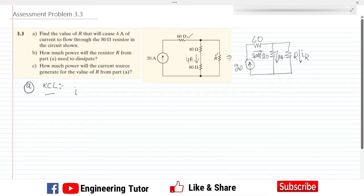the total current, which is I naught, is equal to the current flowing through the 120 ohm resistor plus the current flowing through this R resistor. Rearranging to find the value of IR: IR is equal to I naught minus I 120.